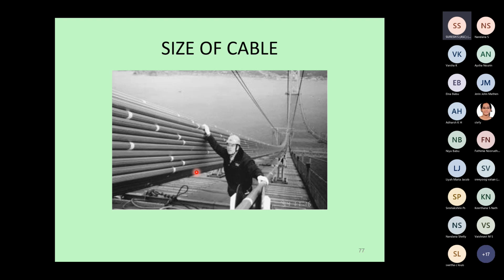With a suspension bridge, you can think of the size of the cable for such large spans like 1 kilometer or something. When the span is more, suspension bridges are ideal. Suspension bridges touch almost 2.5 kilometers of span nowadays. Large suspension bridges. So you can see it's a cluster of a large number of suspenders tied together or woven together, acting as one cable.